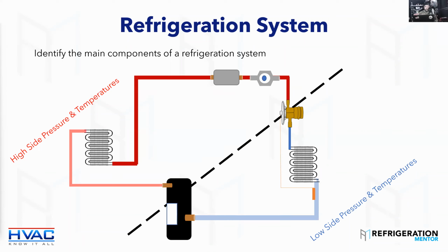Can you have lower pressures on the high side? Is that what you said? Yep. What do you mean by lower pressures on the high side? Lower temperature. Or, dryer. There you go. Yeah, that's exactly right. Maybe my question wasn't very good, but 100%, it's in there. Filter dryer restriction, dirty condenser. Restriction, Brett said there. I missed that one. So exactly. So having that lower pressure or lower temperature on the high side is due to some sort of restriction.